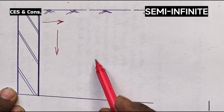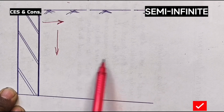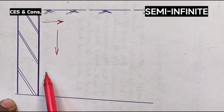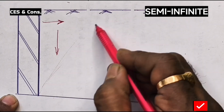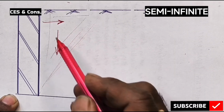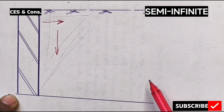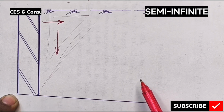So why is this assumption made? Rankine assumed semi-infinite soil mass to avoid boundary effects, to simplify the mathematical analysis, to ensure uniform stress condition, and to consider failure wedge formation without restriction. We know this is the failure wedge. In an earlier video I have stated this. This portion is called the failure wedge. If soil had a boundary nearby like rock or another wall, the earth pressure would change. That's why Rankine considers the semi-infinite soil mass.